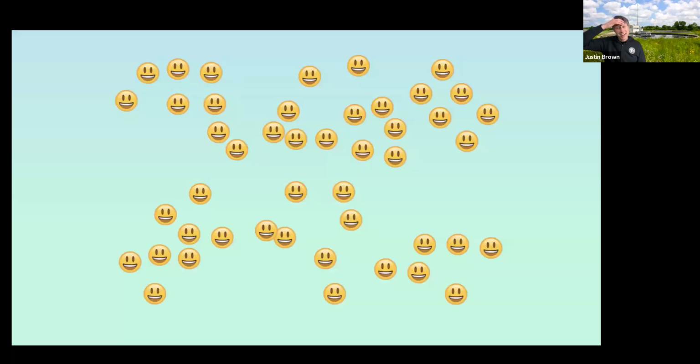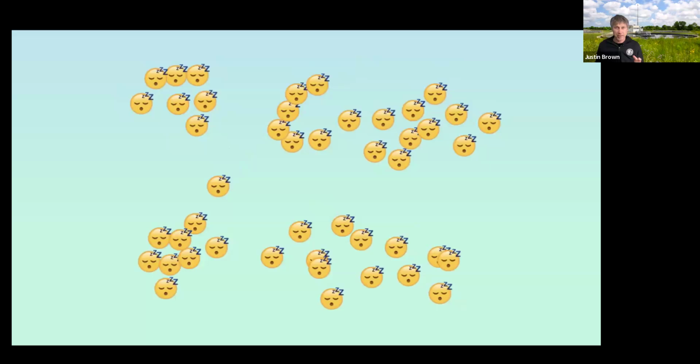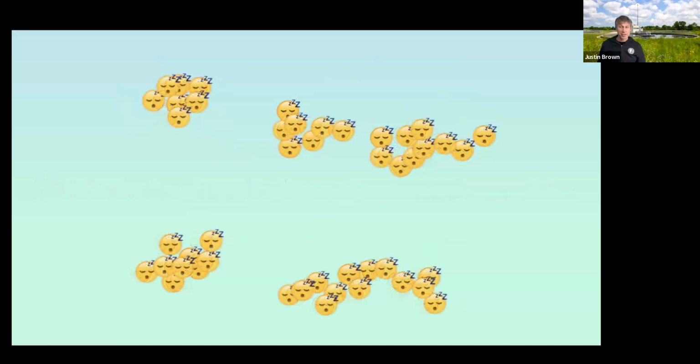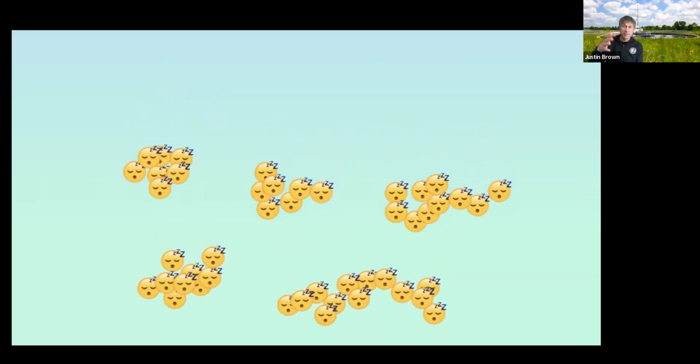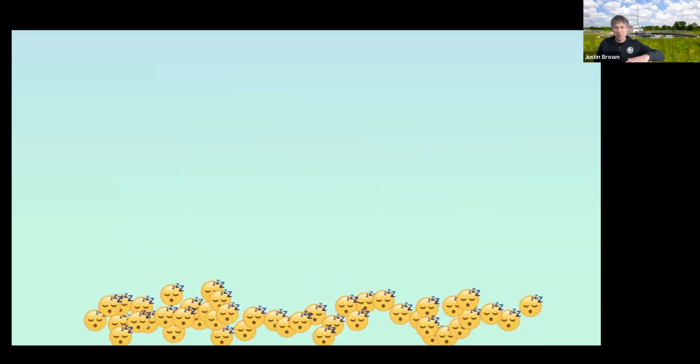So now we're at the end of the aeration tank here, and the bacteria that we set up our process to grow have a behavior called flocculation. And what happens is when they run out of food, they go dormant. And when they go dormant, they form little clumps. And once they've clumped like that, they're able to sink and settle out. And this is what occurs in the second part of secondary treatment, the settling tanks. So they settle to the bottom.